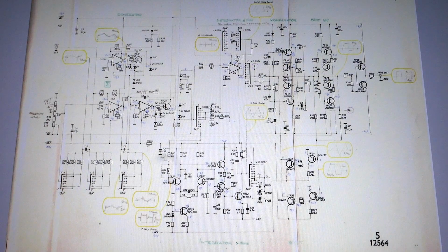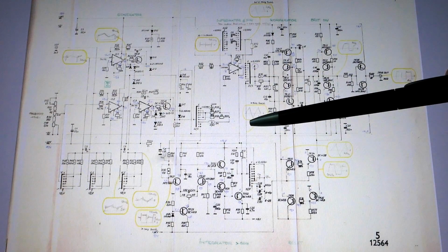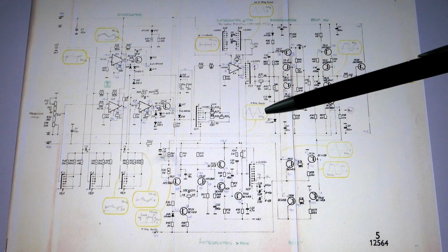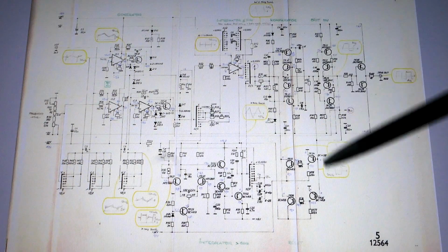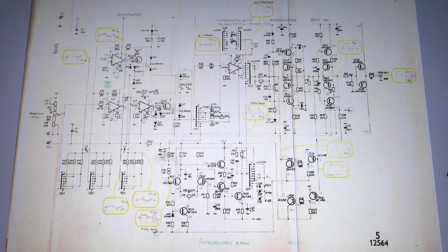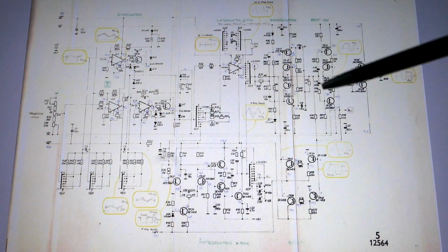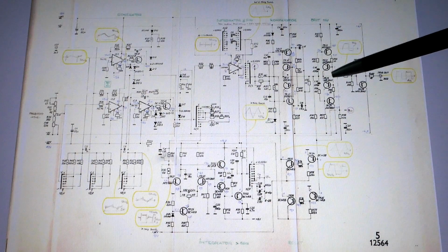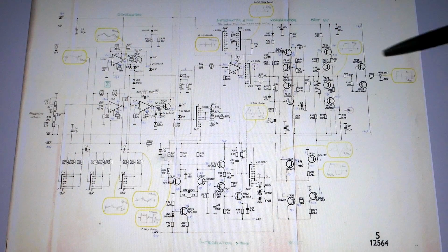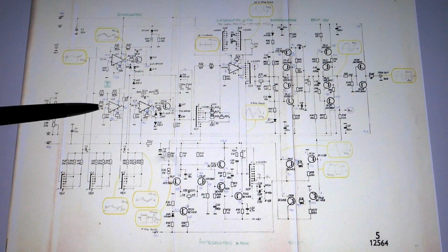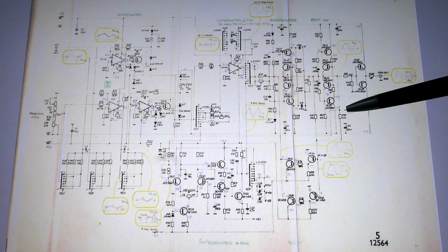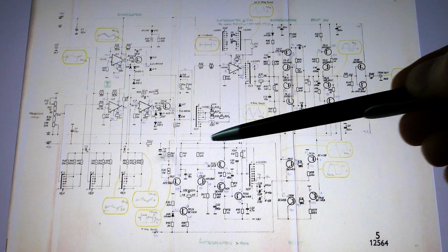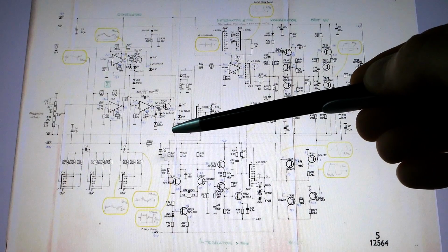And the integrator basically produces a triangle wave, and I guess when the triangle wave hits the peak, it flips this discrete comparator, which is then reset using this resetting circuit, and then there is some bistable multivibrator, and the square wave comes out of this to the trigger output and also to the point B. And I was initially thinking this thing with the op-amps is an oscillator, but it's not, because from the point B there seems to be a feedback going back into this, and this is what makes it oscillate.